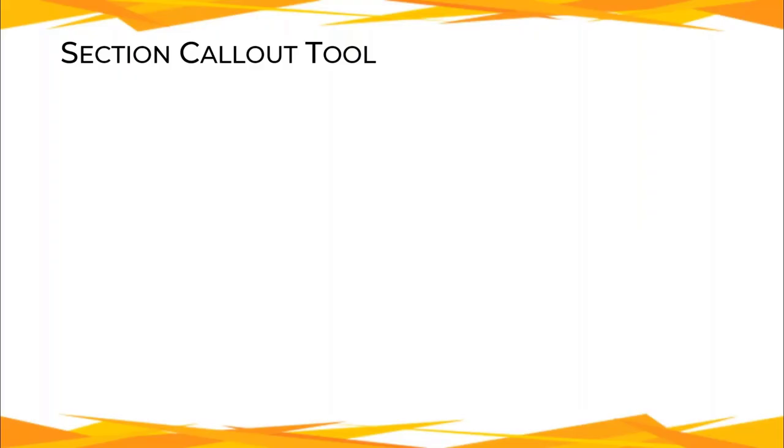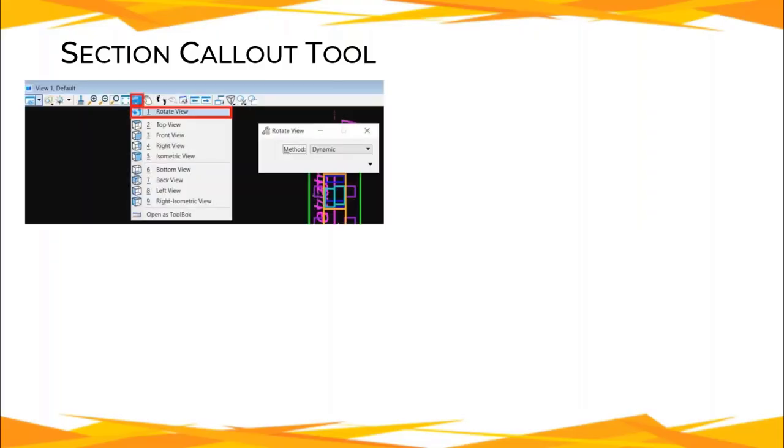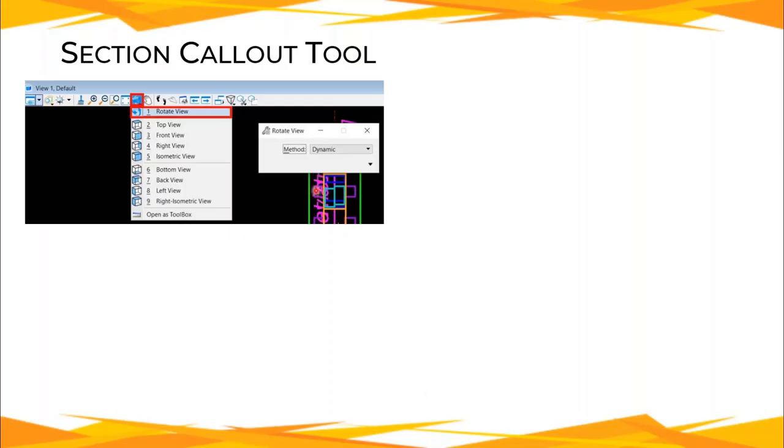So how do we make those adjustments? Well, we can go back to the design model, and then in that view attributes up here, we can go to rotate view, and we can use the dynamic view, which Heather was kind of pointing out earlier, which has that little crosshair. I can snap that crosshair to a point on my pier and rotate it around.